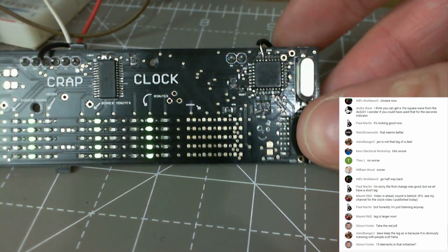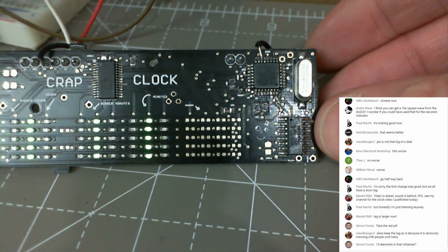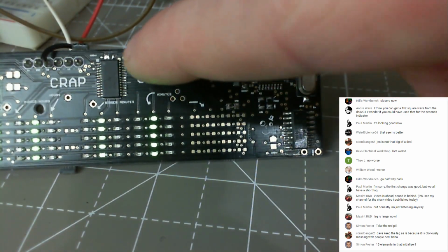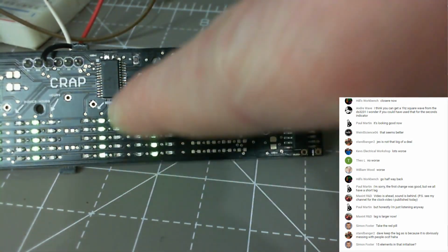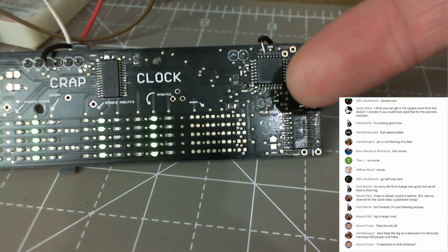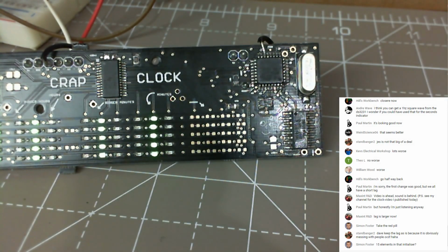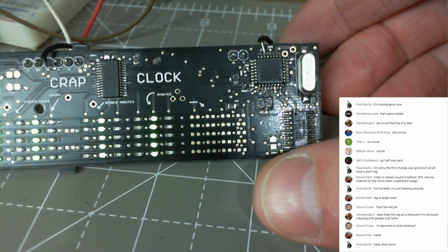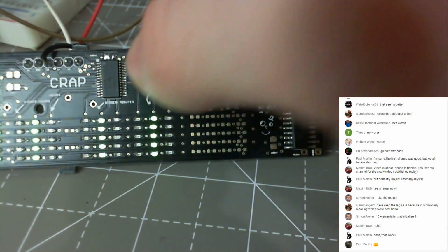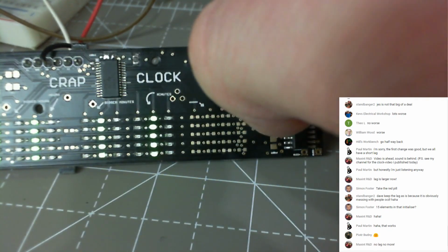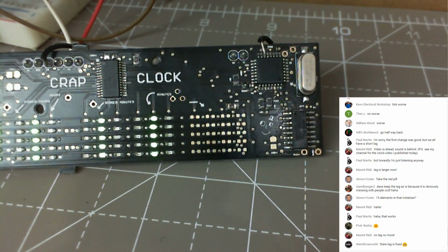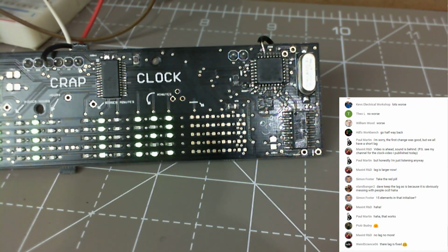So we've got the 74HC here, and it is driving those rows, and the TLC5940 is sinking the current down the columns. And because we're only driving one row at a time, we're not really using a multiplex display. All we're doing is turning one row of LEDs on at a time. And this TLC5940 is sinking all of the columns. So it's not really multiplexed. All we're doing is switching on a circuit one at a time.